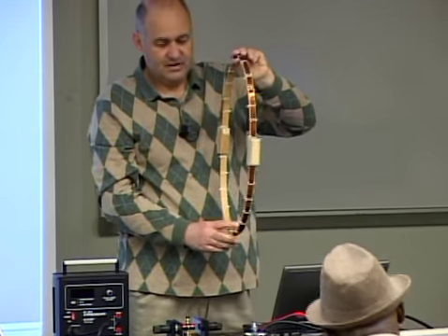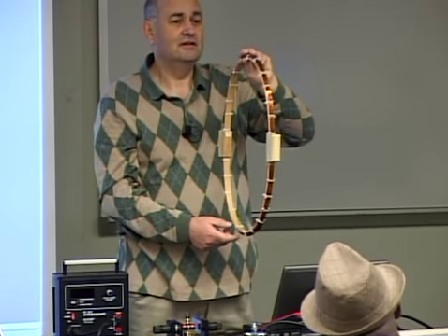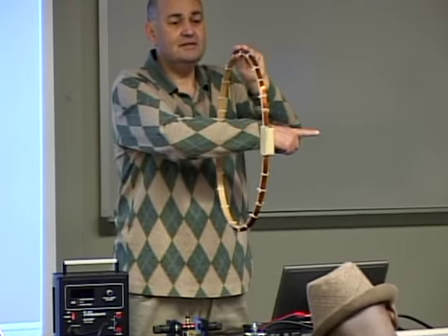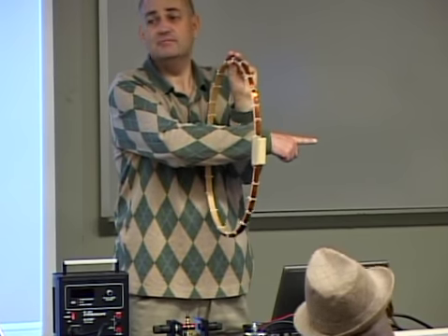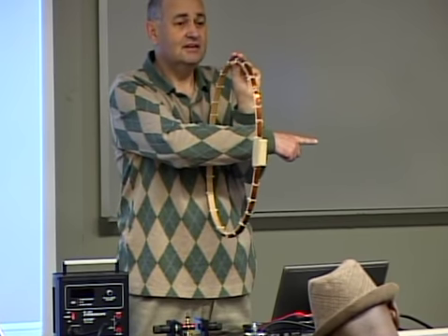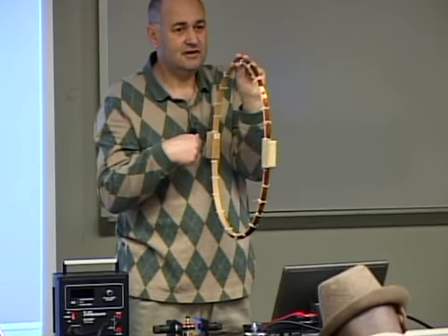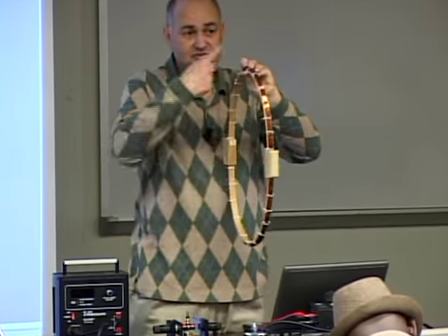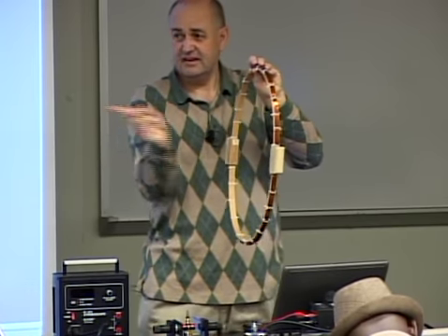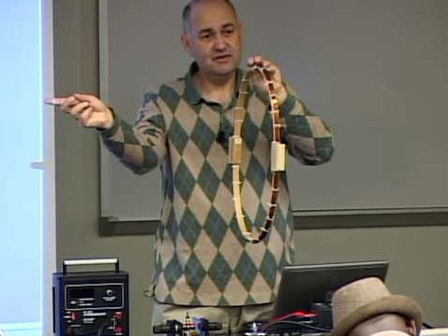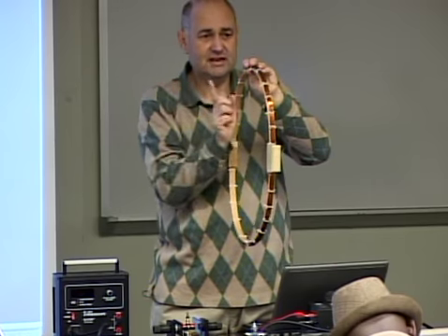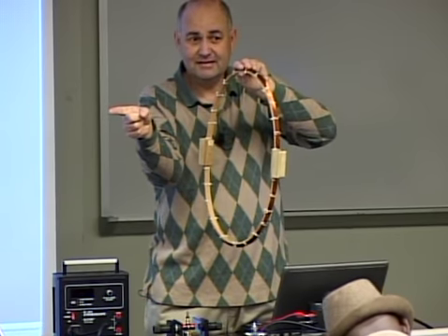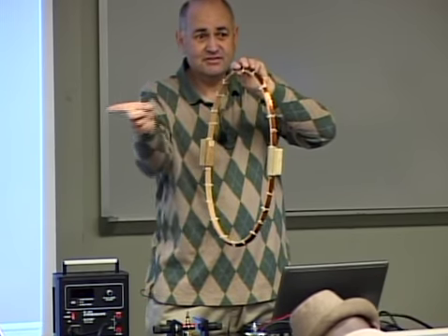Well, what the commutator does, it changes. So right now magnetic moment is in this direction. What the commutator does, it flips the direction of the current. So current now, instead of flowing this way, starts to flow the other way, creating magnetic moment in this direction. It still has some inertia, rotates further, so magnetic moment now is in this direction.